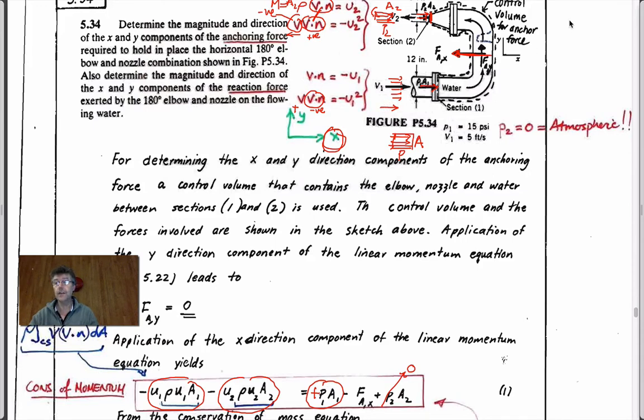And so it's just the way that we've defined the control volume. So the control volume that we've defined is basically this. And so on this surface here, the pressure, whatever pressure we define, has to be acting in this direction. On this control surface here, the pressure has to be acting on the control volume. Has to be acting normal to the surface. And it's outside the control volume, so it's acting in the positive x direction. Right? Okay. It happens to be 0 on the top one, so it doesn't make a difference, right? But that's the reason for that convention.